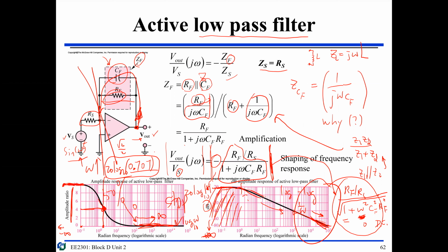Okay, so I don't have to compute. You guys can go there and use your calculator. So 20 times log of 0.707. There's a magic number here. It's called minus 3 dB. Because this is a dB, I know this is minus 3, a drop of 3 dB.